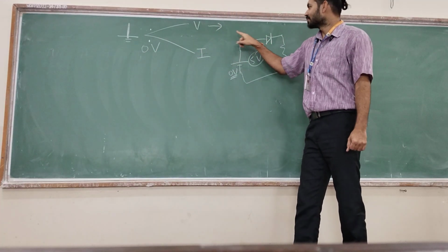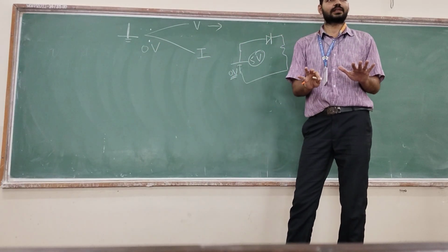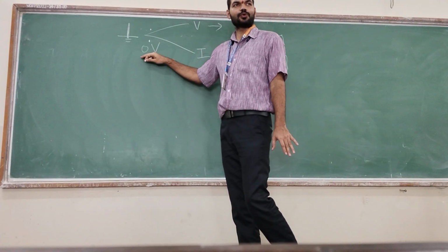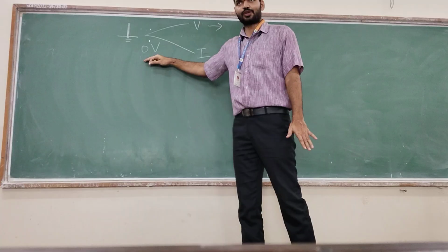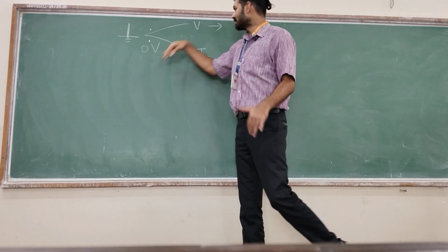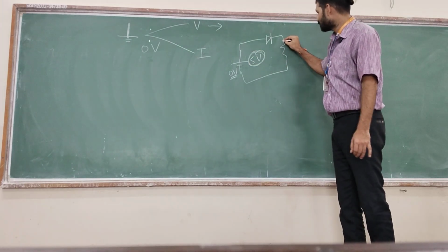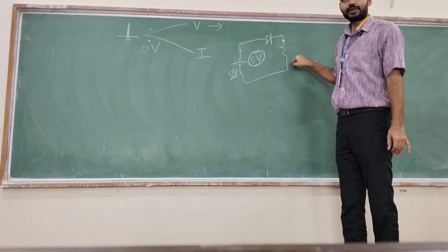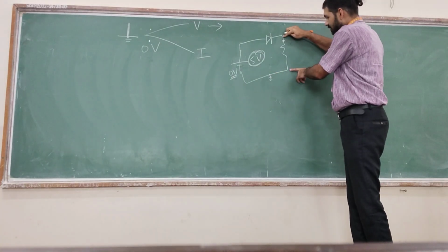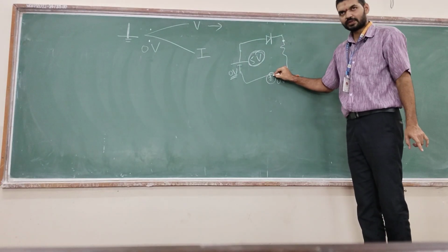Okay. So ground is nothing but the base for all circuits, which defines zero potential, and considering that zero potential as the base, we measure the voltages in the circuit. So if you want to measure the voltage at this point, what is the voltage across this resistor, then we will measure it with respect to ground. So 0 is the ground.